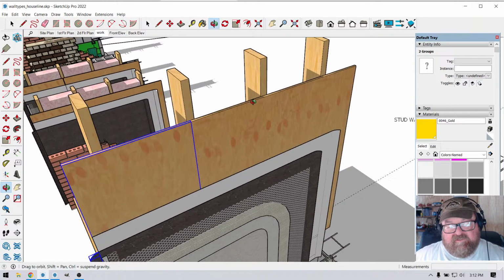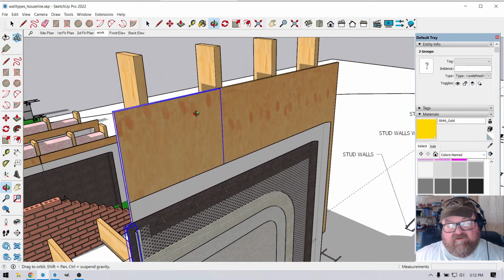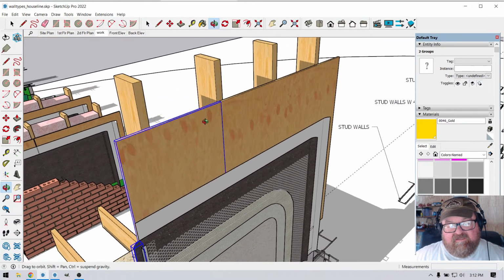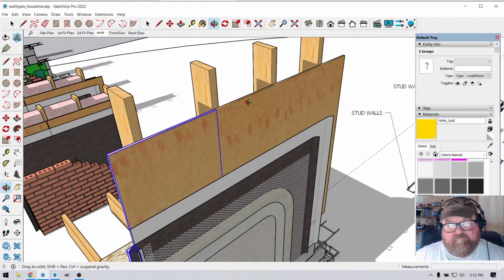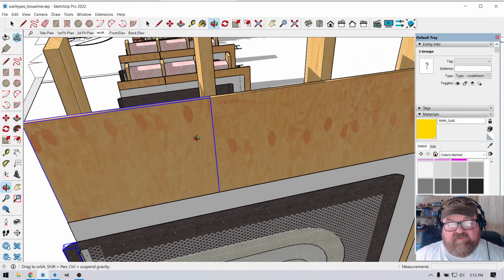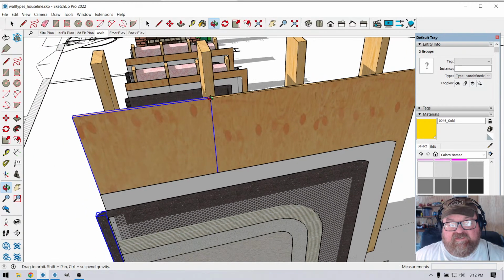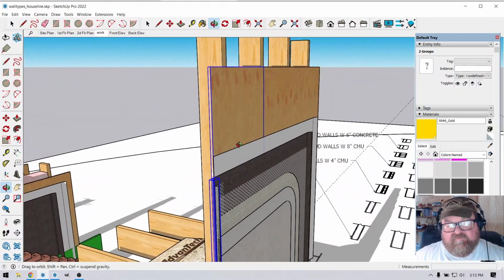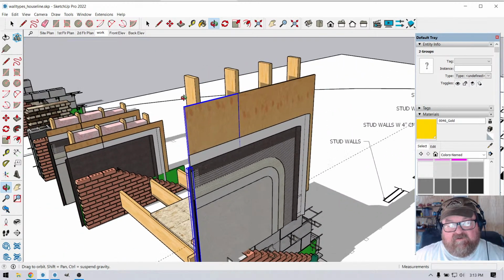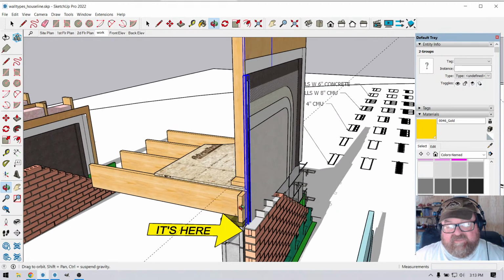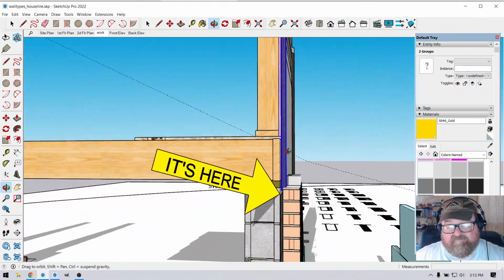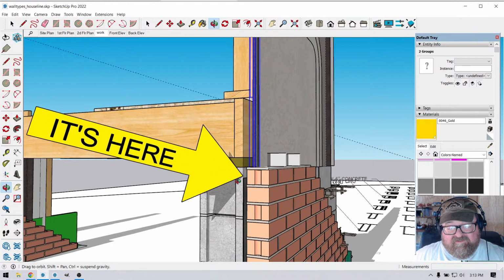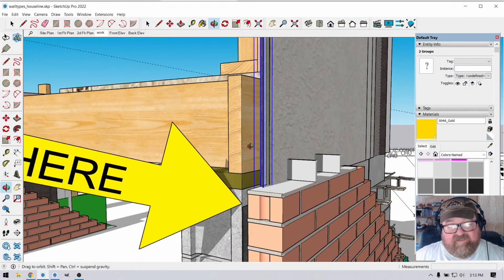You see a lot of people lay OSB down on its side, and so there's a gap here, and guess what? That means your sheeting is only nailed one nail every 16 inches. Is that good? No, it's terrible. Your sheeting should be stood up vertically so that all the edges of it are nailed. Anyway, that's another pet peeve, a disease on the internet. But we're not going to get into that.